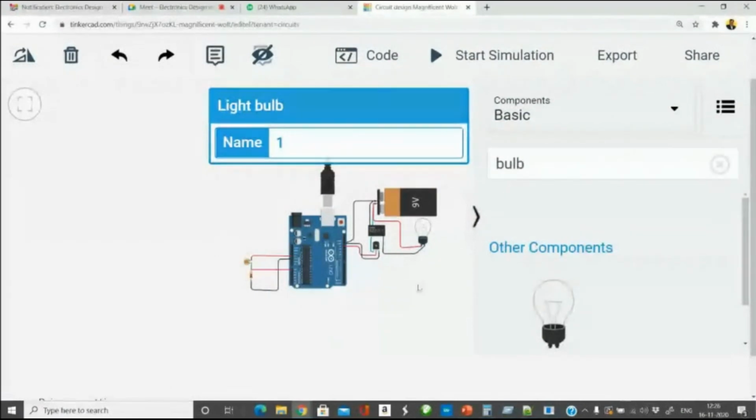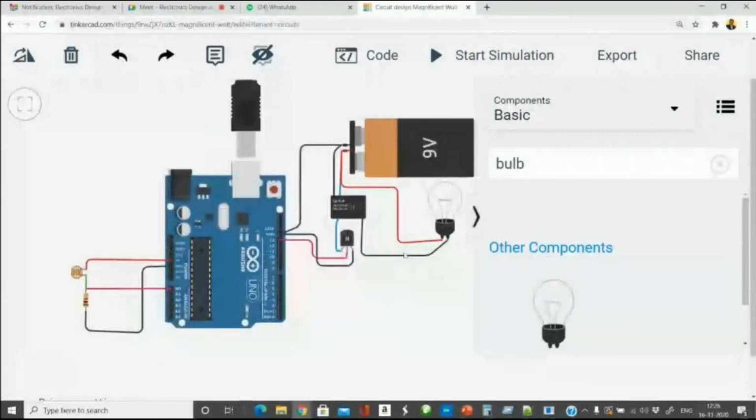Okay, so you can extend the concept like this. You can interface any sensor. Once you get the sensor and interface the sensor to any analog in pin, and then later on you read that analog pin and then you take a control action. Control action is normally achieved by using a relay. Not necessarily that you need to have the relay every time. If it is a high voltage equipment like a street light here, then you naturally need a relay. Otherwise, you can control that by using the conventional port.